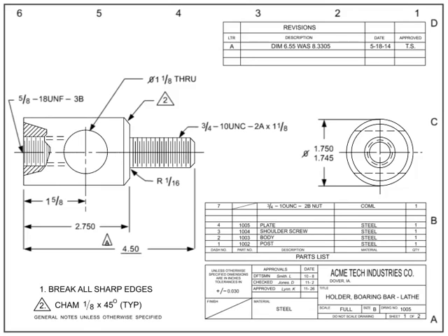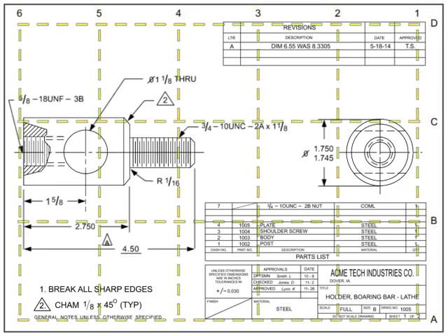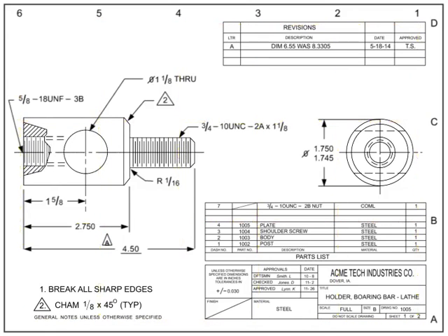Most drawings are broken out into zones using a simple alphanumeric grid. This grid is critical for large, complex drawings when discussing changes or details. The grid helps drafters and engineers pinpoint where information is located. Conventional parts of a drawing include the title block, the revision block, the notes list, the field of the drawing, and the list of materials or parts list.